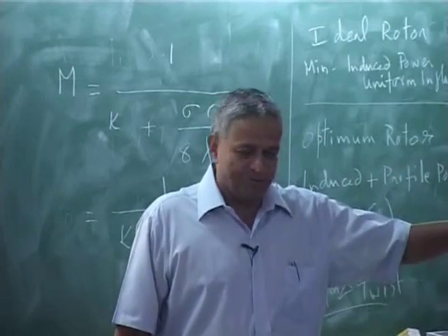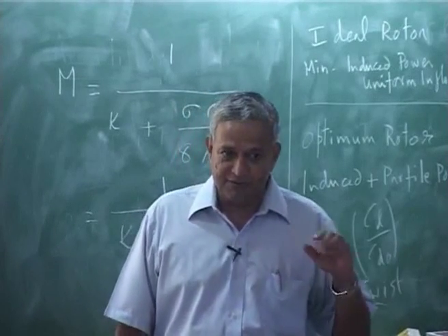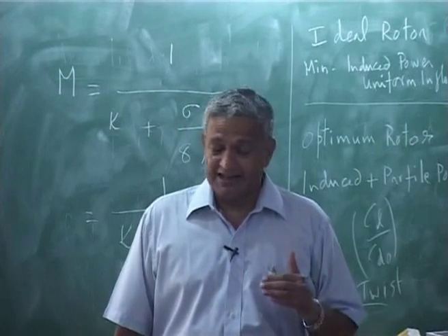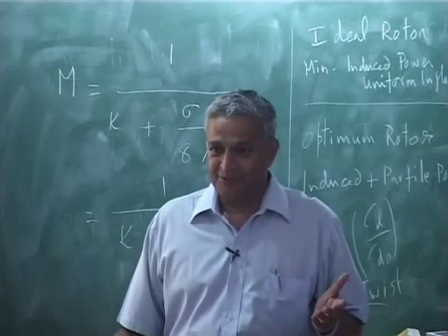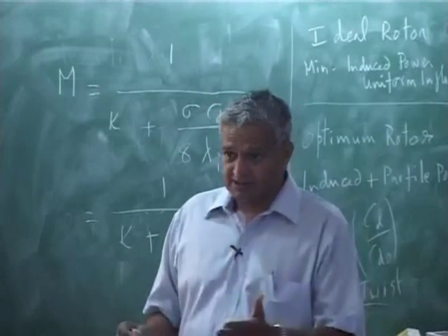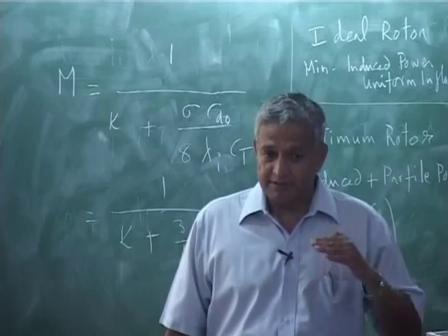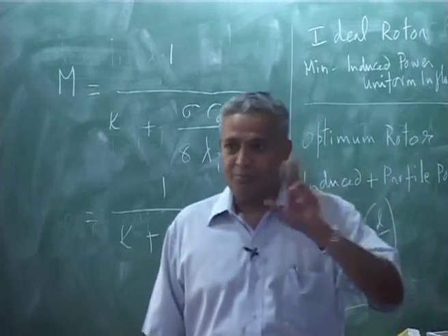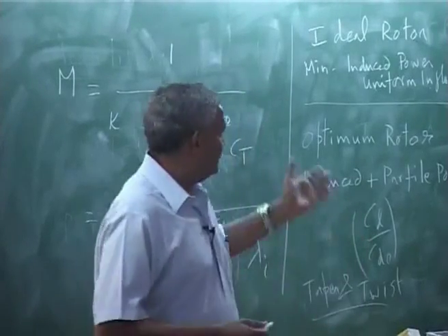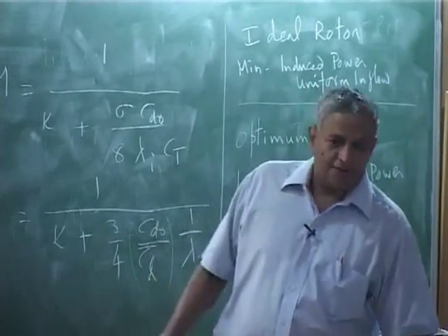We studied uniform inflow, non-uniform inflow. Please understand, whatever expression we got for non-uniform inflow is very good, it is very powerful and it is being used even today for research. I am not talking about just hand calculations, even in research that expression is very good. That is basically relating blade element momentum theory in a differential element, that is all. Then we defined power, figure of merit, etc. Now this is all for hover.